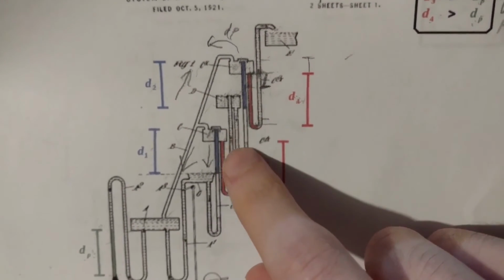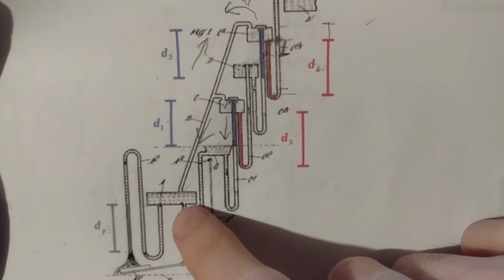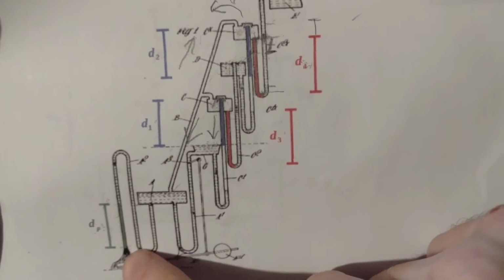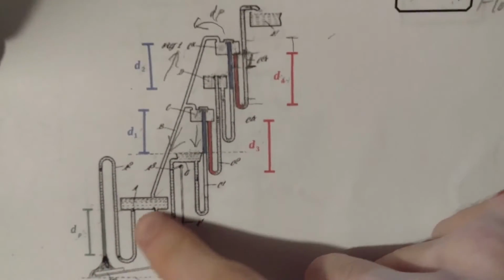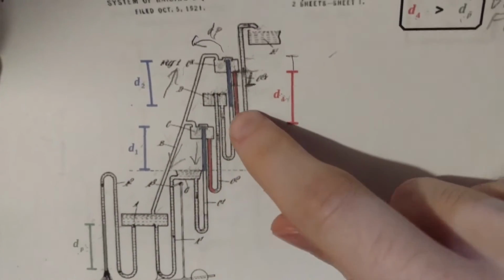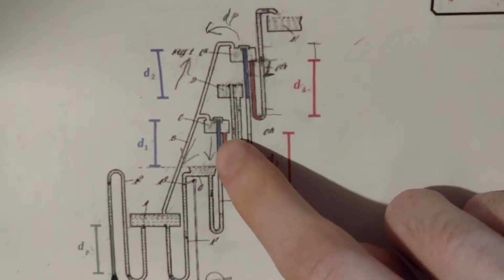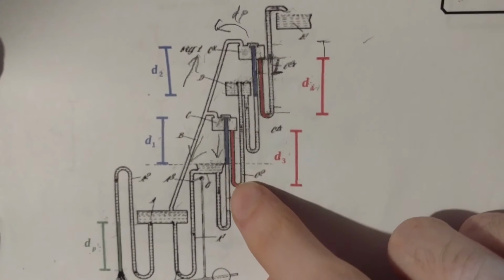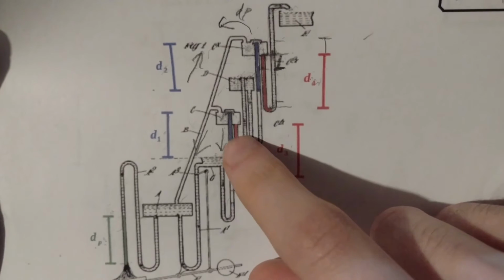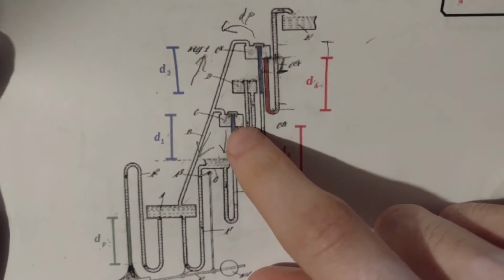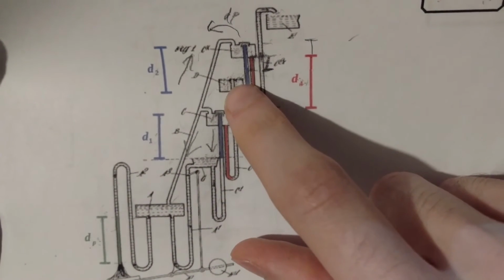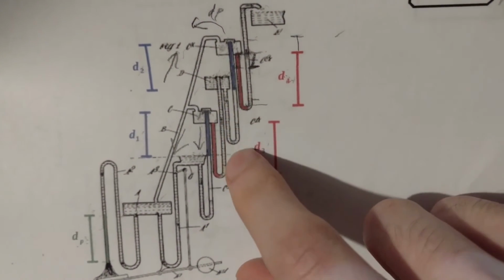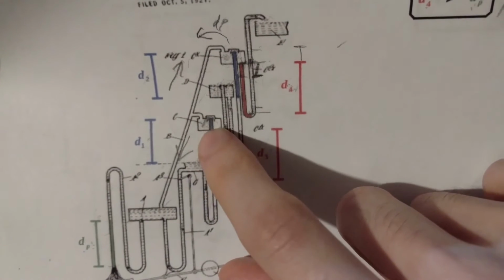So anyways, when this thing's draining out, what will happen is since the negative pressure or suction is determined by that distance, if that suction is more than the pressure that is generated by the height of the water in that tube that's marked in red here, that's what your back pressure is determined by, that distance, and that's what's fighting the air that's trying to come from the outside down into this tube and up into the closed tank here.